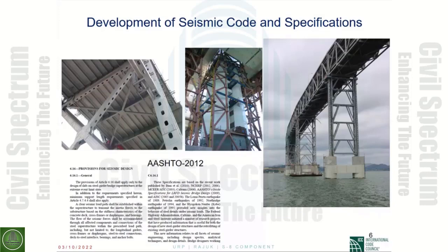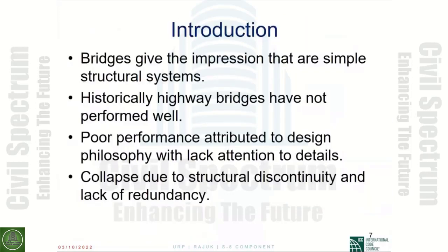The slide or the writing that you see at the bottom of the page is from the AASHTO specification, inside the steel section, 16.6.16, and that will give you the provisions for the seismic design. That's what I wrote for the AASHTO. That involves mainly the load path for steel plate girder bridges, and that's what we're going to touch on during the talk today.